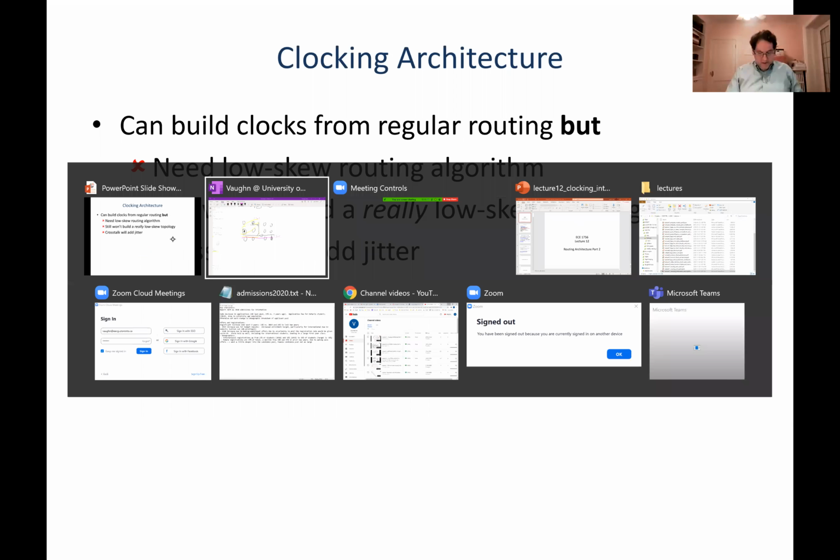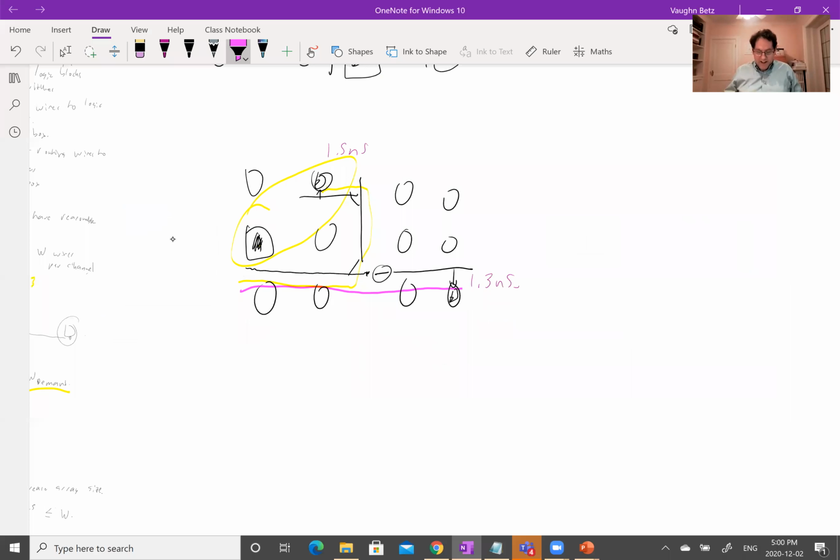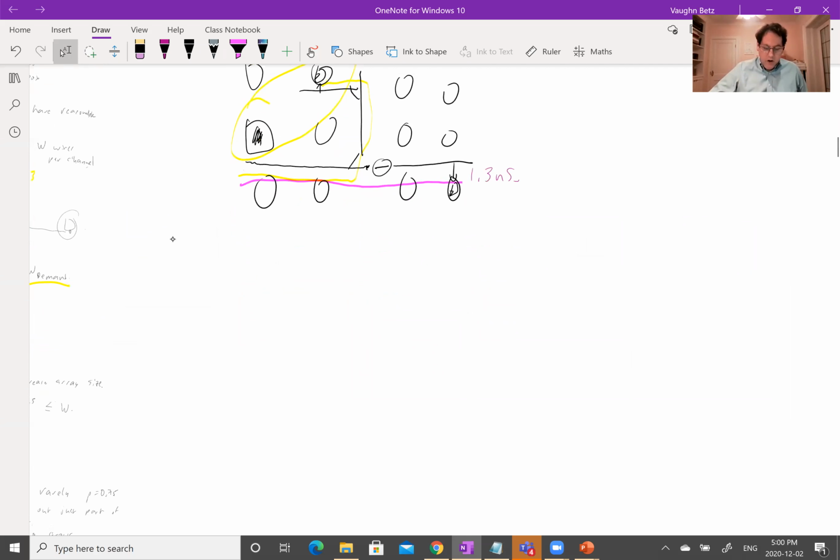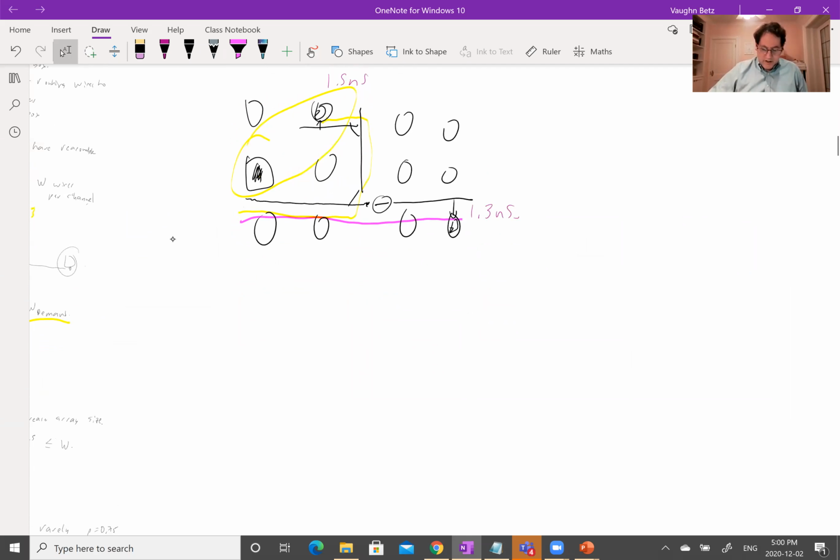Yeah, that is a great answer. That's exactly right. It's two signals that are influencing each other. They're coupled through their capacitance, either capacitively or inductively coupled. Both can cause crosstalk. On chips, it's capacitive crosstalk that's dominant. Inductive crosstalk actually can be important at the IOs and on the board, but on the chip, it's capacitive crosstalk. Okay, so what do I mean by that?